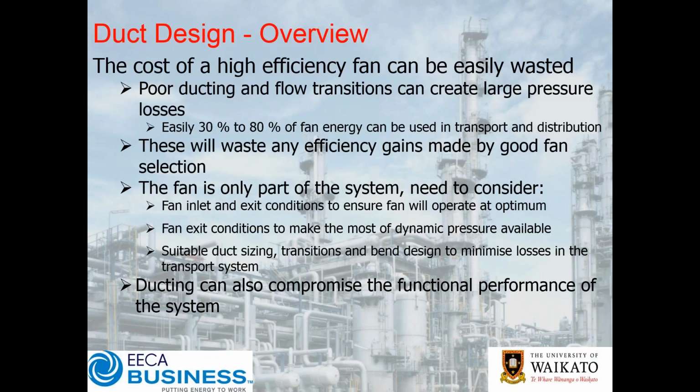It's not uncommon to see 30 to 80% of the fan energy, so that's the shaft power going into the fan, being wasted on transport and distribution as opposed to actual end use. Not too dissimilar to some of you that are thinking, gee, I thought compressed air was the only system that can waste a lot of energy. Well, a badly designed fan system can be just as bad. You can waste all the efficiency gains that you make by having good fan selection by mucking up the design of the rest of the system.